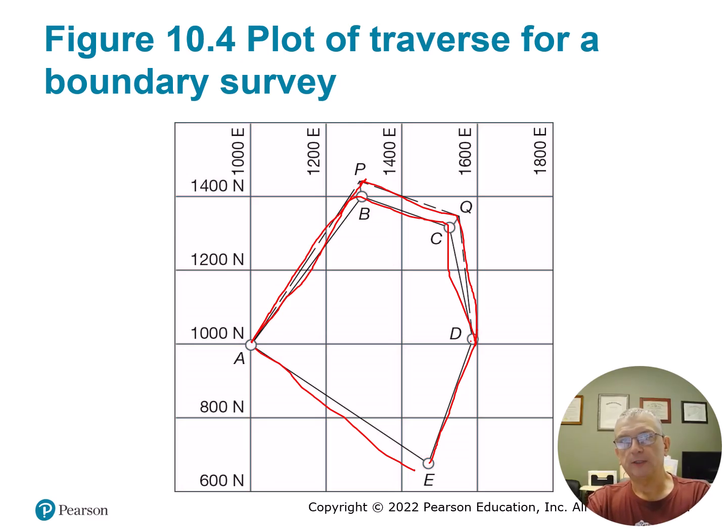So you'll not only be determining bearings and distances between your adjusted traverse, but also you'll be determining coordinates on your side shots, and then we'll be determining bearing and distances between some of those side shots.